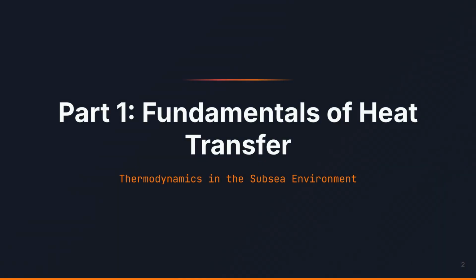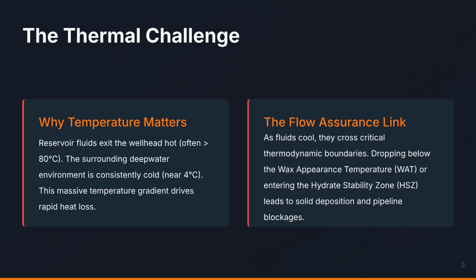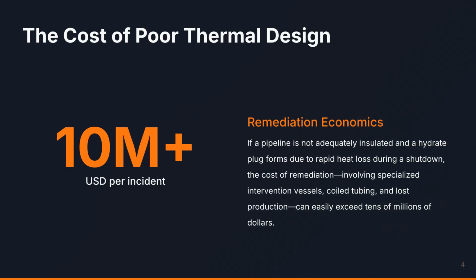We begin with Part 1, covering the fundamentals of heat transfer and thermodynamics in the subsea environment. Deepwater operations face a significant thermal challenge. Reservoir fluids start hot, but lose heat rapidly to the cold 4-degree seawater. This can lead to solid deposition, like waxes or hydrates, causing costly pipeline blockages. Poor thermal design is extremely expensive. Remediation of a single hydrate plug incident can easily exceed $10 million in lost production and specialized intervention costs.